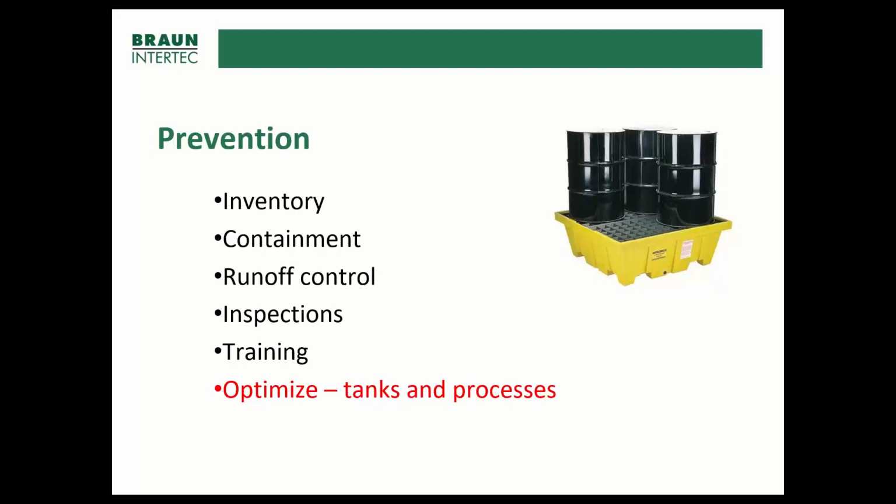The other thing we do to help in prevention of spills is we have to look at our runoff control. Figure out where you have your materials stored or in use, and then figure out where they are going to go in the case of a release or a spill. Is it a floor drain? Is it a surface stormwater inlet? You have to inventory and be aware of where these key receptors are on your facility.